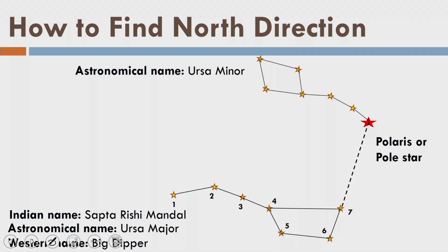Okay. Further, we have given you some more information about that. Now we have found the pole star. There is a zenith for you, there is a pole star in the sky, then you connect this line, that is your meridian. If you make this meridian from the zenith to the north star or the pole star, then on the horizon this will connect you to the north direction at your celestial horizon. Well, that is the idea of how to find the north, and opposite to this north direction there will be south. Okay. What about east and west?